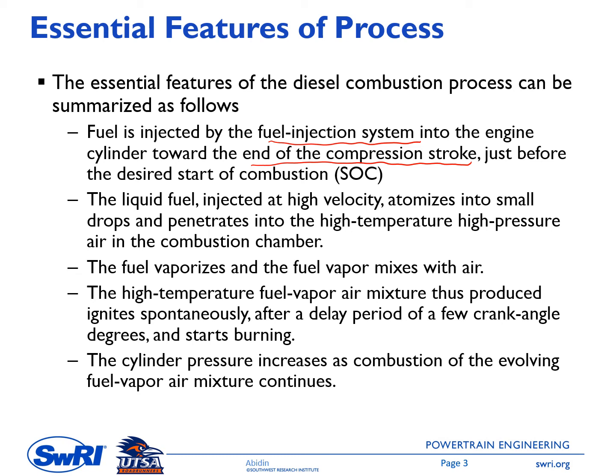And then, because this liquid fuel is injected at a very high velocity, so much higher than the velocity of the surrounding gases, which consists of air, residual, and maybe EGR. So because of this very high velocity difference, there will be a force acting on the liquid fuel that can break this fuel into small droplets, and this process is called atomization. And then this small droplet will penetrate farther into the high temperature and high pressure air mixture.